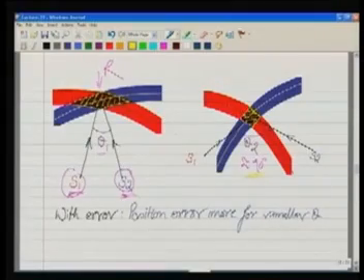So a good GDOP or a good geometry could be one where one satellite is on top and 4 satellites on the horizon. So this is a good geometry. It will give very good geometric precision, or the dilution of precision because of the geometry will be less. While if all the 4 or 5 satellites are hanging up there, in that case the dilution of precision because of the geometry will be large.